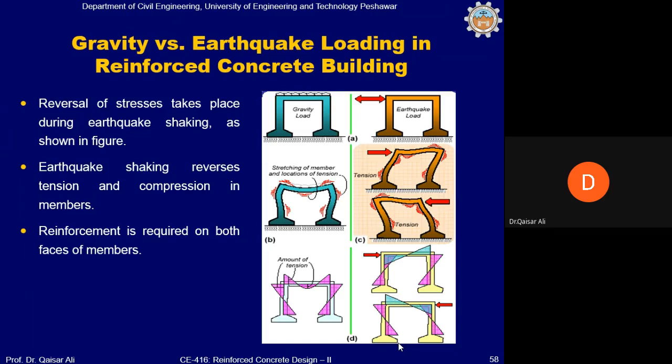This can create problems, and this is what we have explained in one of our slides, that this can cause horizontal irregularity, and these irregularities must be taken into account. In reality, in high-rise buildings, most of the time these walls are not coming on the beam column center line.